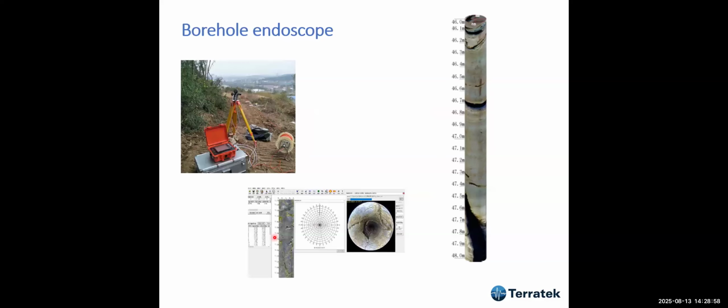The other thing that is very much used today is a borehole endoscope. And like the endoscope that I use in medical procedures, we have a camera. The camera enters the borehole, and it's going to show you what's going on. You can measure. You can have a much better description of the lithology.